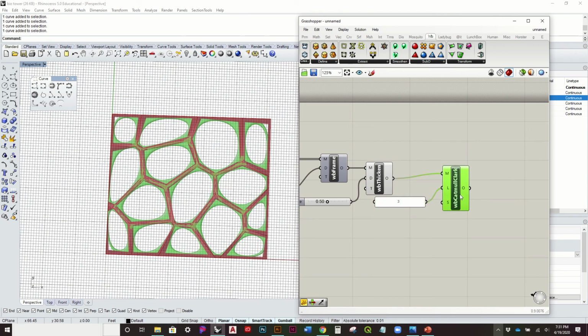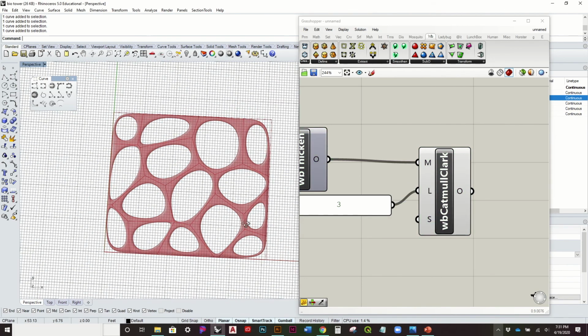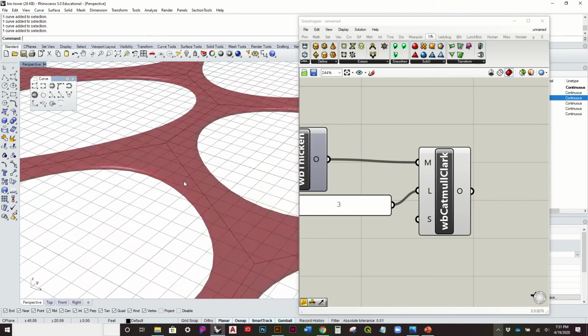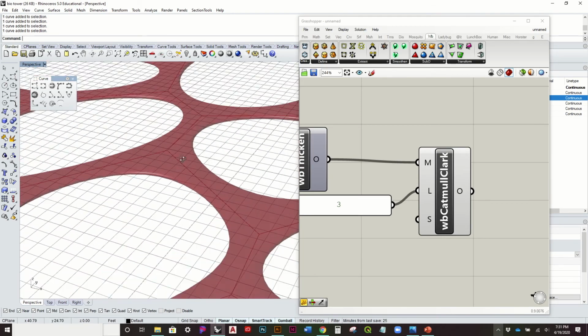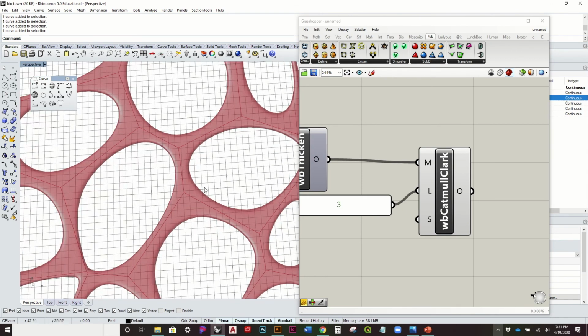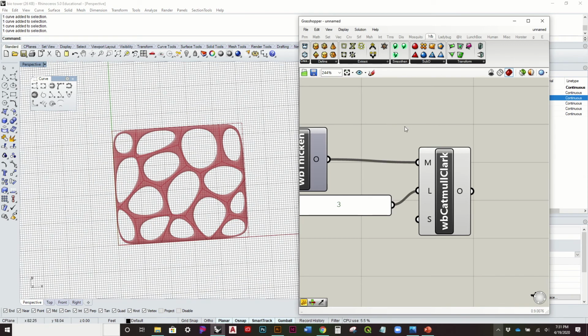And you'll also see that the other setting that comes out of this is whether you want it fixed, smooth, or corner. It defaults to the smooth. That's really kind of why you use that. So it does that as a default already. But now you can see that our surfaces are nice and smooth, both vertically in that extrusion as well as some of these areas. So we really lose that very hard edge, which is great.